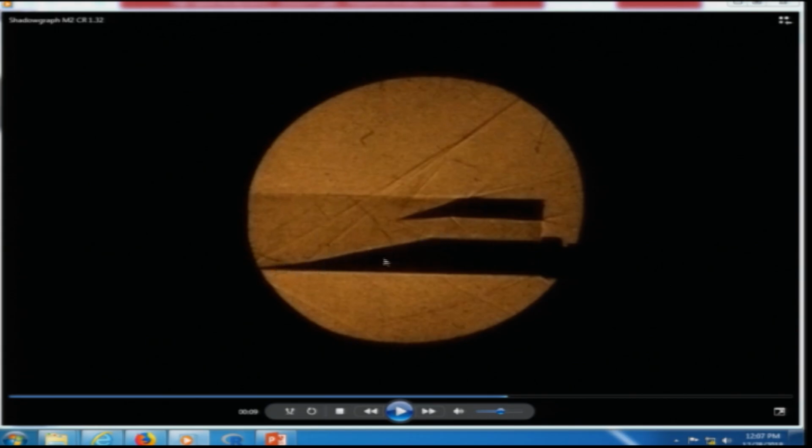In this particular case, I have used two ramps, one from here and another from here, that is a double ramp. Once you start a supersonic flow at Mach 2, many waves are generated from all the corners, and they coalesce into each other and become very strong.